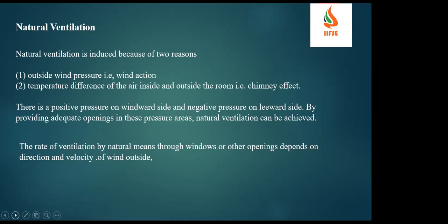So generally, how does this natural ventilation happen? It depends on the inside and outside pressure difference of your work area. If the pressure inside your work area is more, no air will come in, because the pressure is higher inside than outside. If the pressure inside is low, automatically the outside air will come in. Then temperature difference of air inside and outside the room, or the chimney effect.